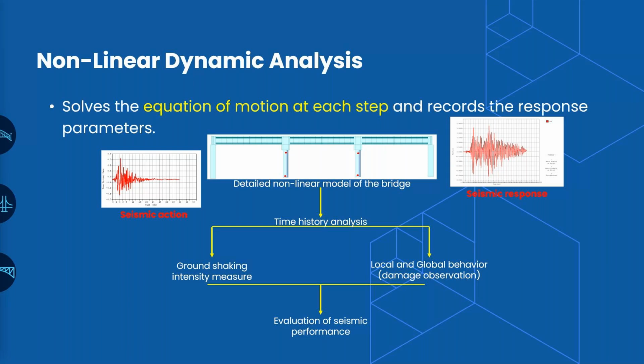So it does not account for many of the parameters such as the accumulation of the damage. As you know, an earthquake has an impulse at each second, and the forces are accumulating, and so is the damage in the structure. This type of representation is not possible in the case of pushover analysis.